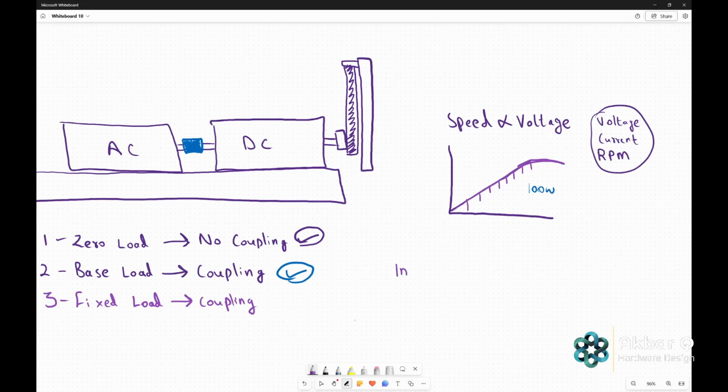As I said, the generator efficiency is the output power divided by the input power, but the input power is multiplied by the efficiency of the motor. Sheet number 3 allows us to get the efficiency under load.